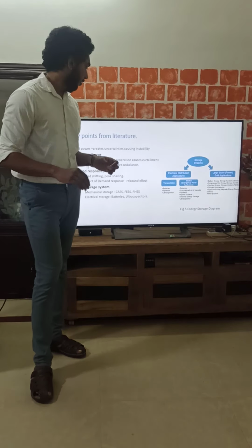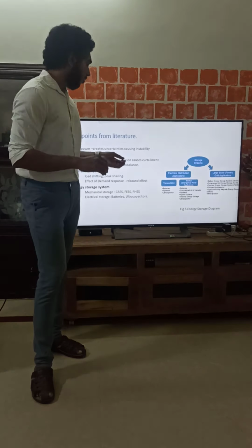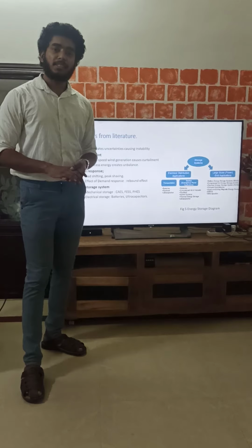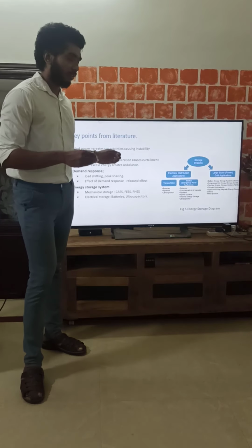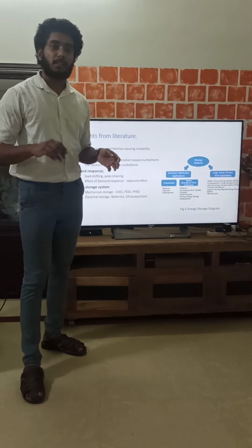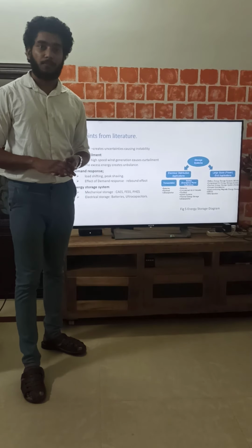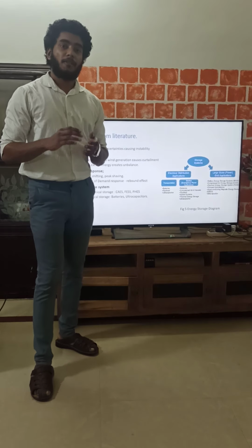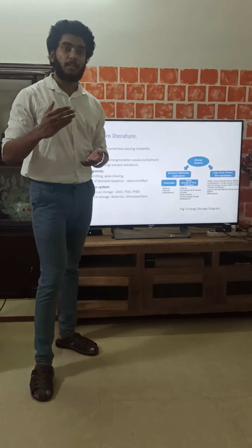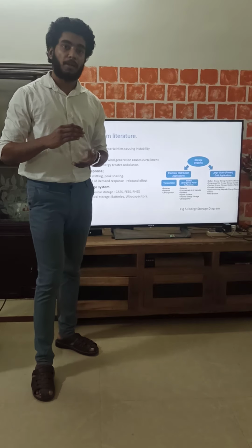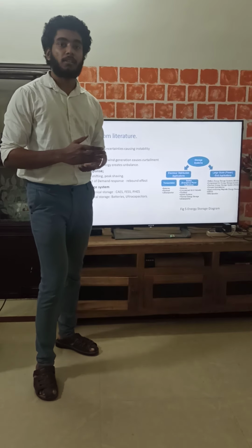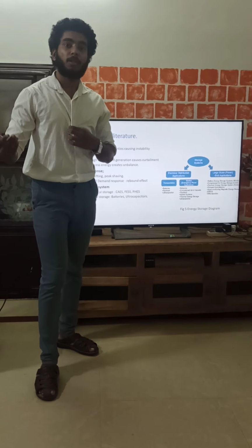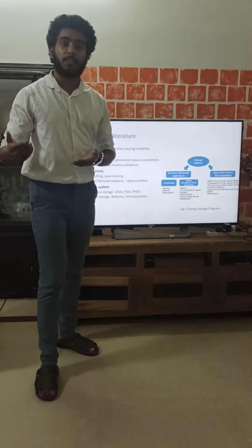That means some of the loads are reduced, and there is an effect or phenomenon associated with this demand response. That is the demand response rebound effect. So what is this rebound effect? The rebound effect is when we shift demand from the peak time to another time, and the delayed demand creates some uncertainties or spikes when it is shifted to the other time.